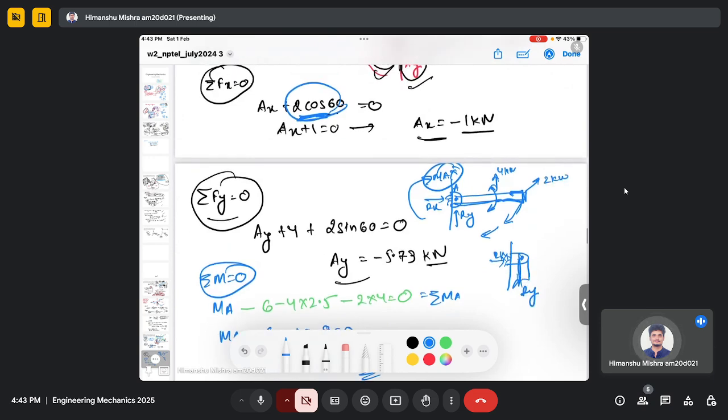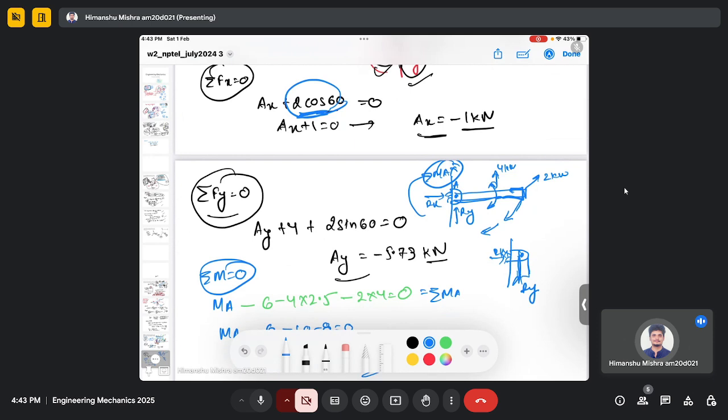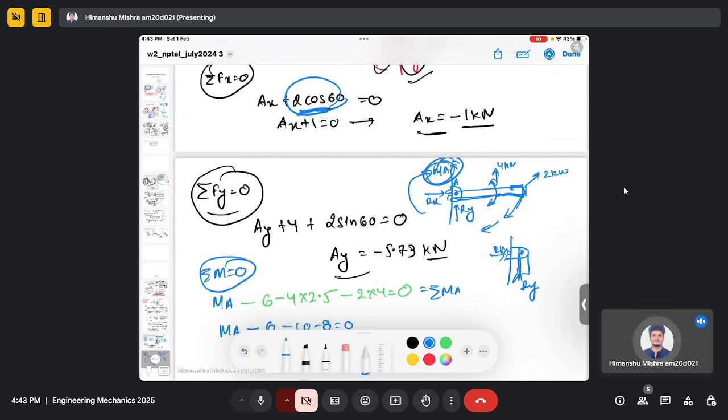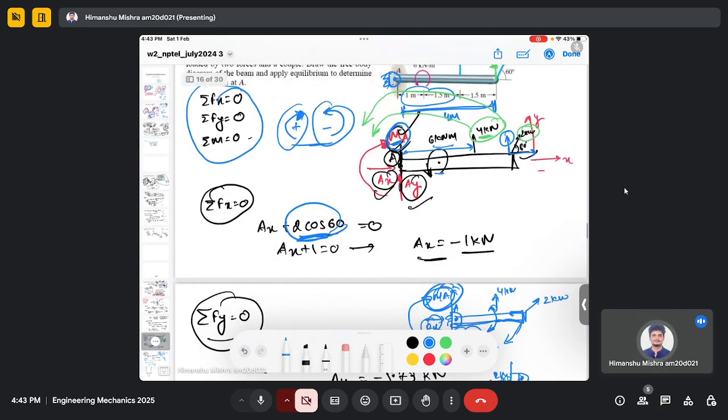So if you consider the pin joint, for this instant you don't need to consider the reactive moment at point A. You just need to calculate Rx and Ry. But for the fixed support, since the rotation is constrained, you need to consider the moment here at point A, because this moment is constraining the rotation.